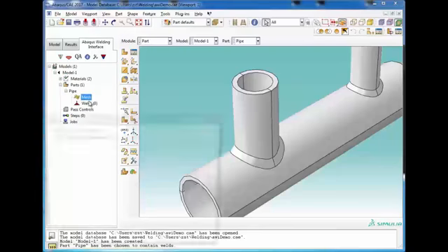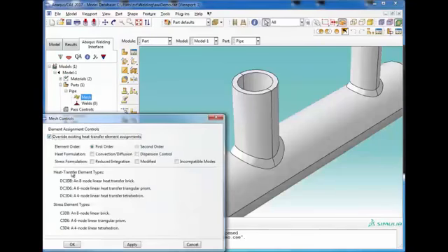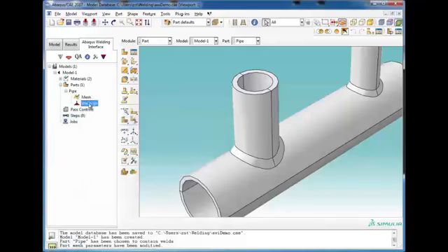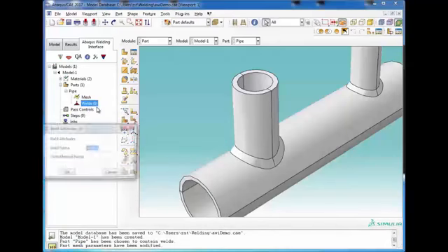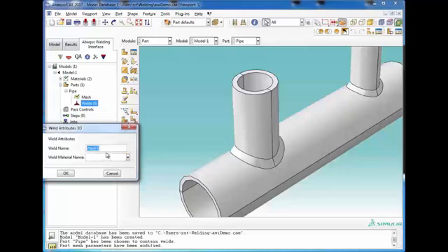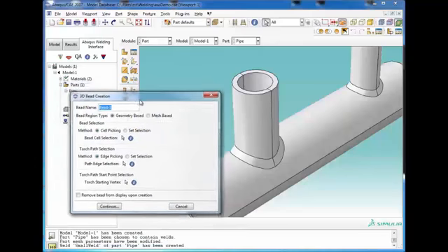which is really just assigning the element type. Now if you've already got element types you can assign, you can just hit OK, but in this case I don't, so I'm going to use just first order heat transfer, and then later on when the stress model is created, it'll use the corresponding stress elements. Okay, so the next step is actually to define the welds. So we'll start with a small weld, give it a name, give it the material, and then you'll see the bead selection